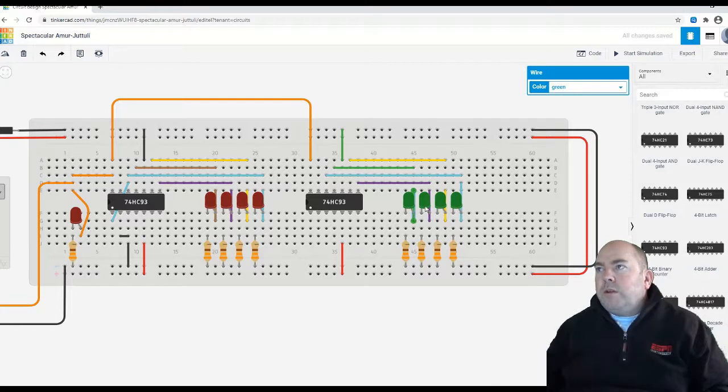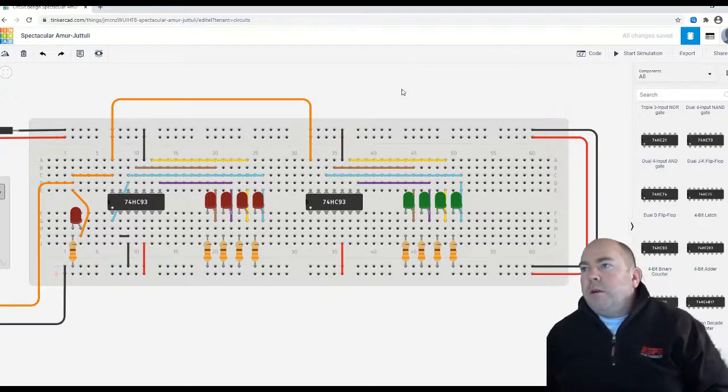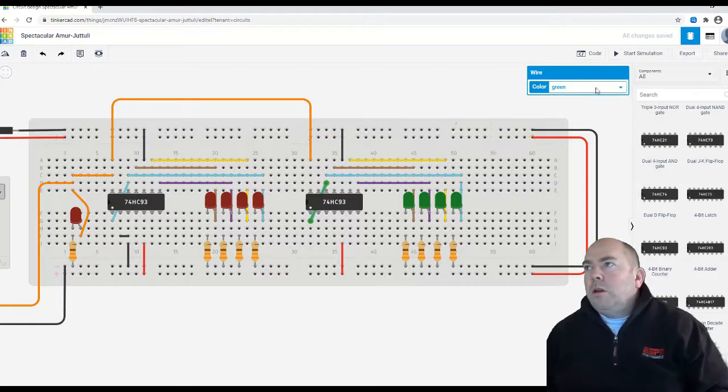Once I get this done, I'm just going to test this. The black wire. Alright, so these should both now just count up to 15 if everything is good. Oh, I got a crossover here. This one goes to here. That's my turquoise wire. And then disable the resets for now.